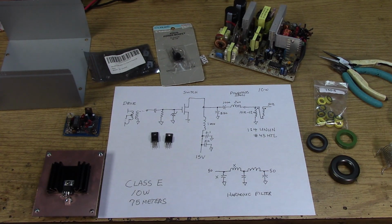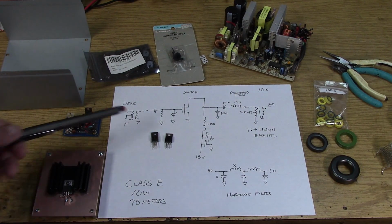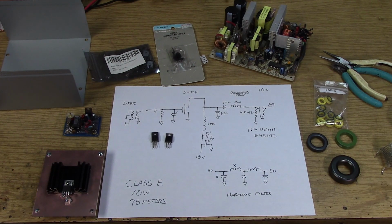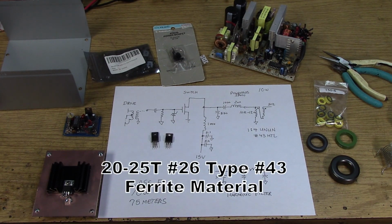Also, I've got a grid leak and some protection on the input for the gate. This is probably a 15 to 18 volt Zener, and this is probably a 1K resistor and just a coupling capacitor, like a 0.1. We do need a choke in the drain circuit. We can make a nice little 1 millihenry choke.